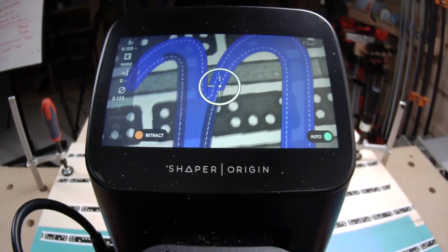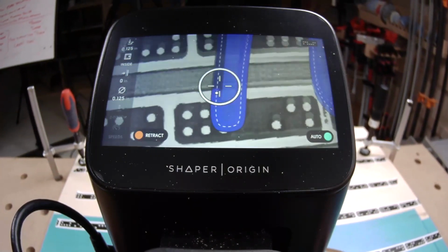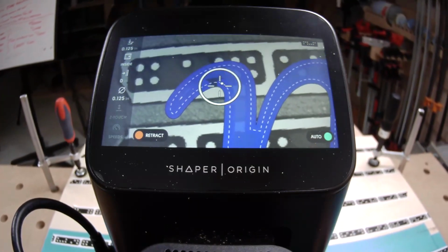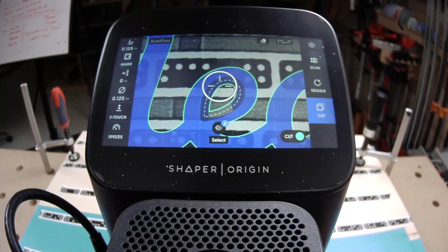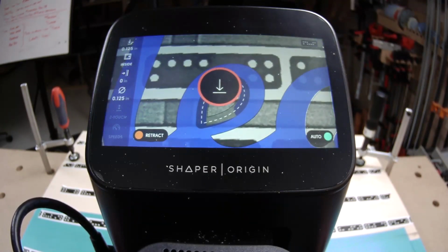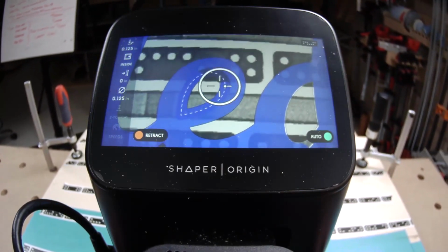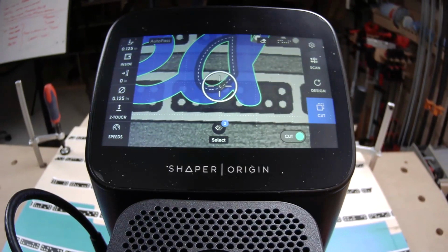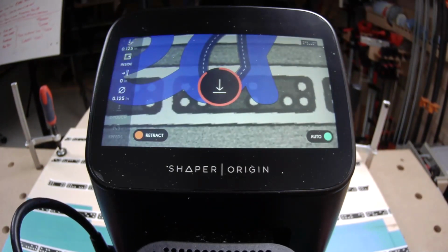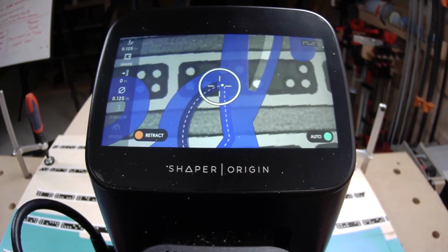And the veneers are very delicate. They're kind of difficult to stick to a tape board to use. Ramon developed a really great method using spray adhesive to hold that stuff in place, but a down cutting router bit especially will help keep that veneer stuck in place, but only as long as that veneer isn't too thick, because when you're only taking a shallow cut, there's not much material that you're really pushing into the cut.